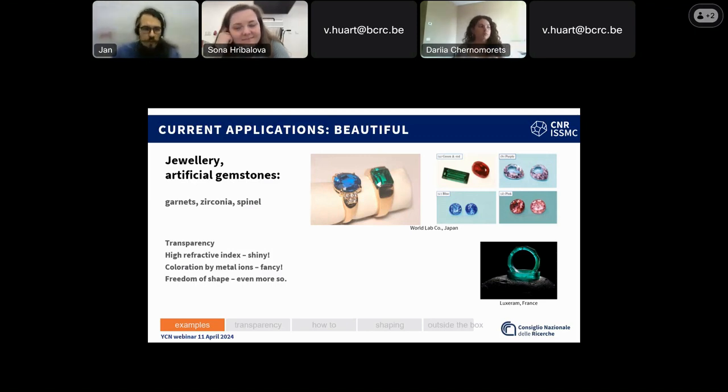Just look at the standard sintering in air, normal pressureless sintering. That's most likely not going to get you to transparency. Why? Well, because you don't have enough driving force to remove the last pores, even if your material was really good, say, had a uniform and nice microstructure in the green stage. You're probably not going to get complete removal of pores unless you do something more.